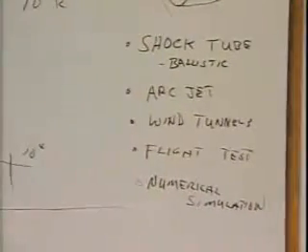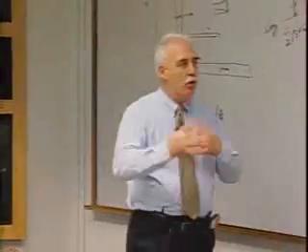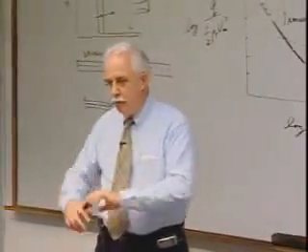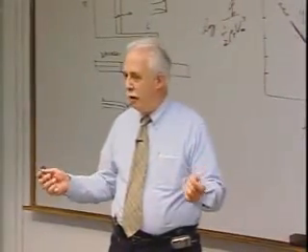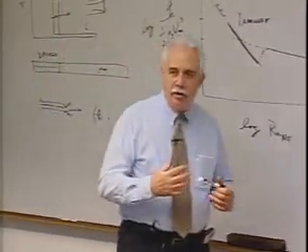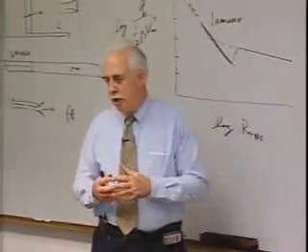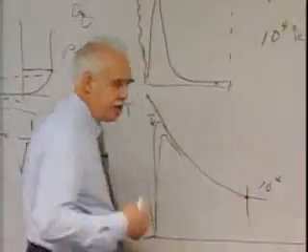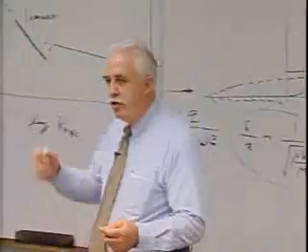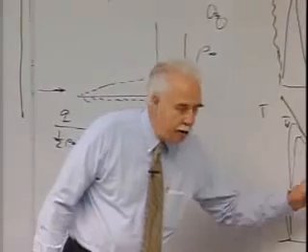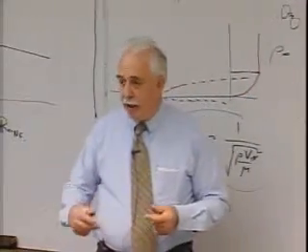This problem of non-equilibrium is kind of beyond numerical simulation, in my opinion. Now, you can correlate things, but I like to point out the limitations. You don't just go get a computer program and calculate everything, because there are some very fundamental things missing. The way one gets reaction rates, for example, dissociation rates or recombination rates, is to go into a shock tube. As you approach equilibrium, the concept of temperature and the equilibrium constant makes sense. So you can relate forward and backward rates. And you do diagnostics spectroscopically on a concentration, and you get rates. And it gets to be kind of complicated.